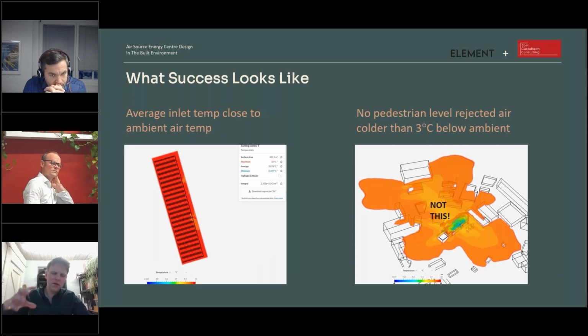There's a few indications when it comes to recirculation that we're doing the right thing. One of them is that we can notice that the average inlet temperature on the underside of the heat exchangers is as close as possible to the ambient temperature. Now, if we see that the average has dropped substantially, it's very likely that we're seeing some recirculation. That view there is directly underneath the heat exchanger, clipped on all sides. So all we're seeing there is the average inlet temperature of the model. And that's one of the first things that fundamentally I go to see that we're on the right track.